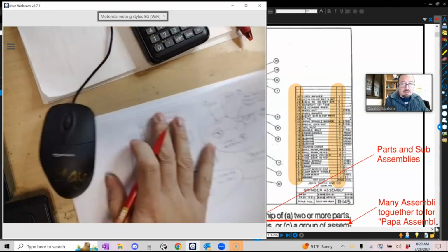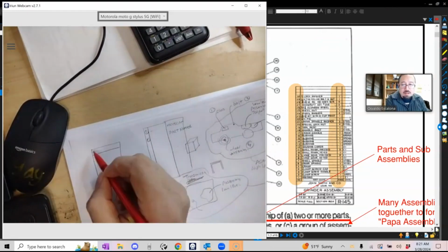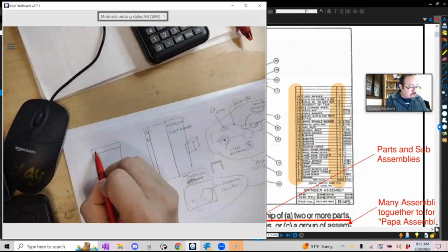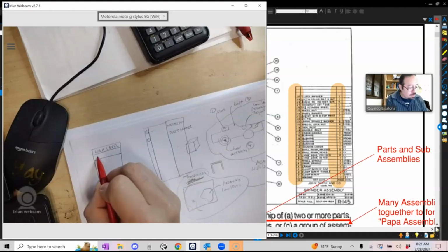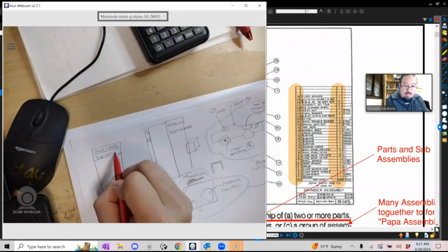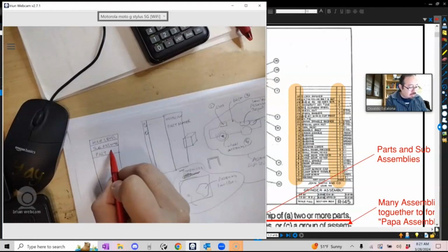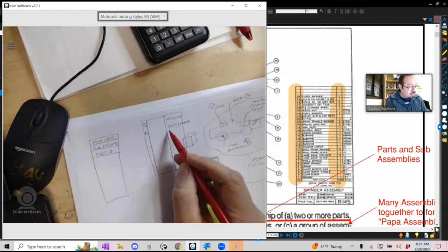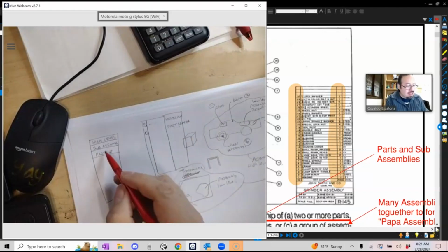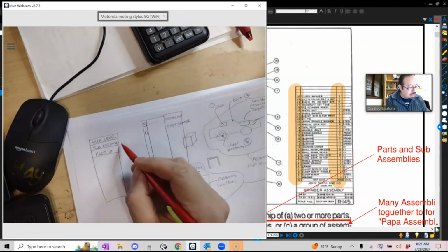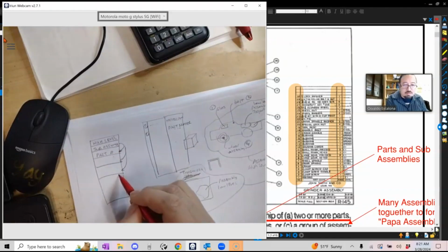And then when you actually get to produce the drawings, you're going to have different types of drawings. One of them is going to be your high-level assembly. Then you're going to have drawings of subordinate assemblies. And then you might also have drawings of each of the part numbers, right? Each of the parts that you call out. So if you have 20 parts, you will have 20 different part drawings. You will also have a subassembly that is calling out the parts that live within the subassembly.